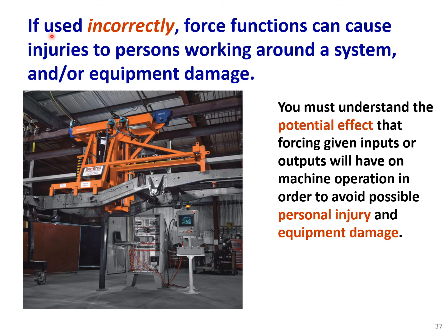But forcing, if used incorrectly, can cause injuries to persons working around the system and or equipment damage. So basically, forcing should be done very carefully. It is not a good practice to do random forcing, so we should know the consequences.